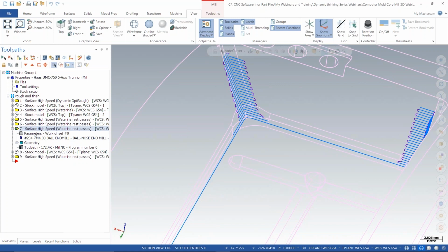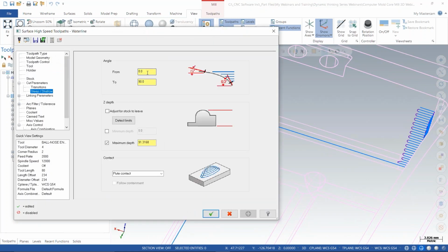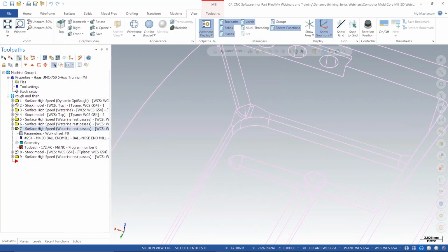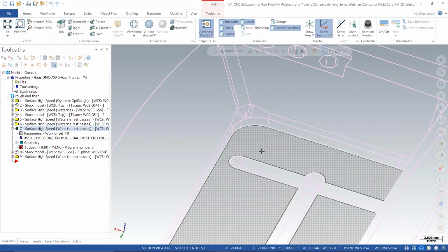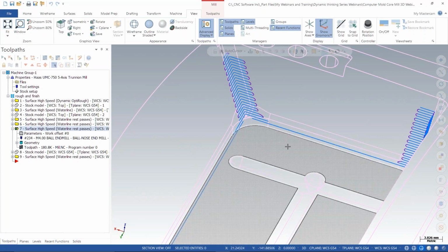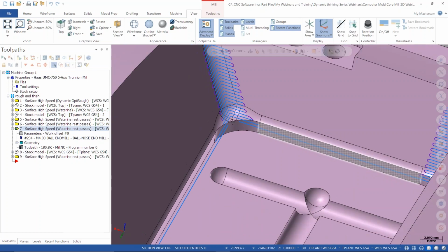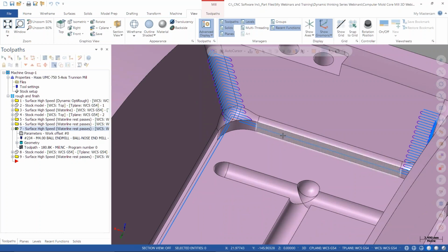So for the next toolpath, maybe you're thinking, okay, that's a shallow pass. As a Mastercam user, we know we can come in here and I'll just say machine everything from maybe 10 degrees to 90 to get rid of that pass. And I update it, and it comes back, and it's like, oh man, what's going on? It didn't do it. Well, the reality is that is a steep pass against this wall down here. So that's not shallow, it's steep. It's deceiving, right? As a human, we saw it and said, oh, that's shallow. No, it's steep against this wall.